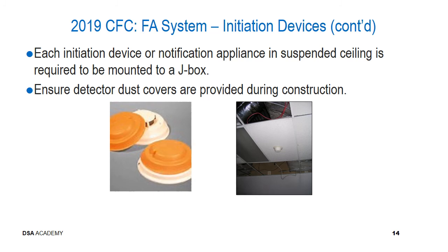California Electrical Code Section 760.30 for fire alarm circuit identification notes that fire alarm circuits shall be identified at terminal and junction boxes in a manner that helps to prevent unintentional signals on the fire alarm system circuits during testing and servicing of other systems.